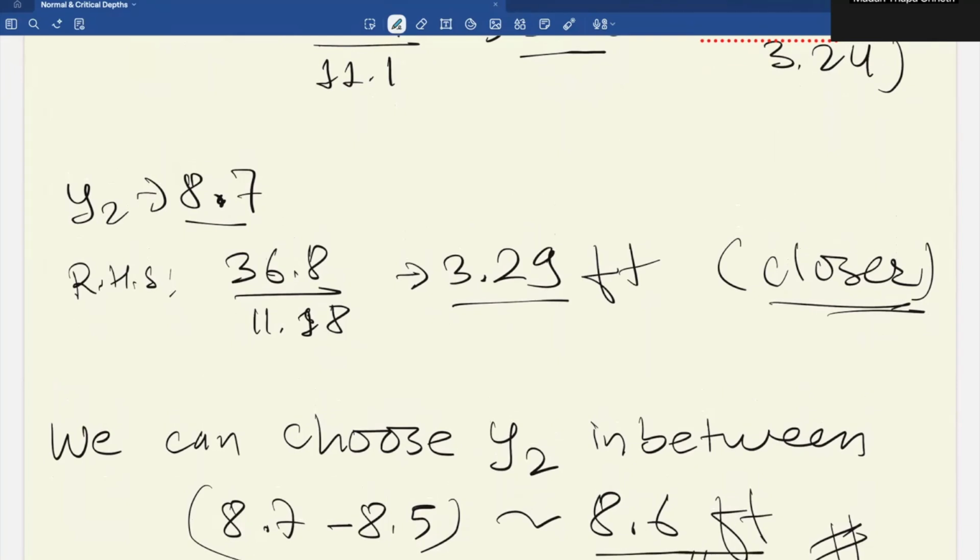So in this question, one of the important things you need to consider is that maybe you didn't see the values for S and n and consider them as unknown. The question already mentioned they are constant, so you don't need to worry about that. You can eliminate them through the ratios. So this wraps up our critical depth and normal depth recitation class. The big idea is Manning's equation, which is used everywhere in these four problems.